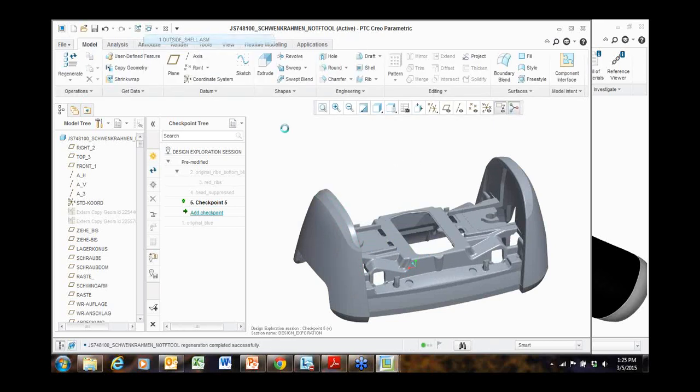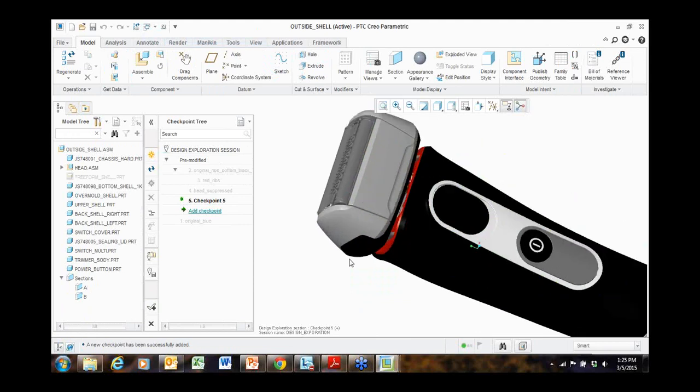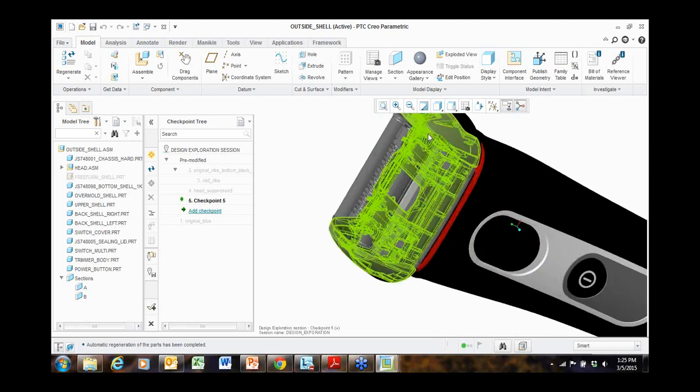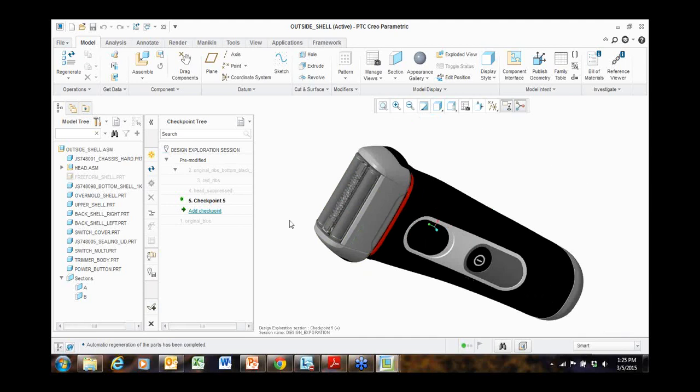And similarly, we will go back to our assembly, and just to verify those changes, they have been propagated to our assembly. I will do a regenerate again. And right here we have the chamfer that we just created. Gentlemen, again, we can make multiple changes to our models, and all those changes can be stored in a single checkpoint. So after this, the next thing that we are going to look at here are the different tools that we have available here in our checkpoint tree.